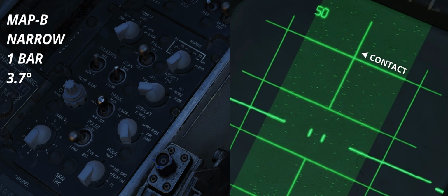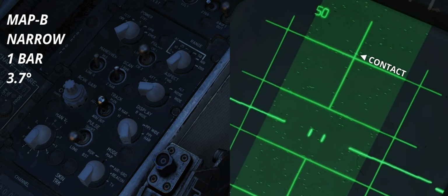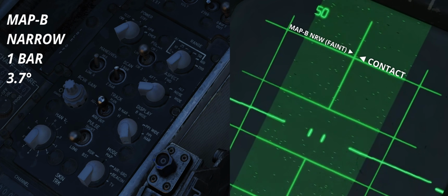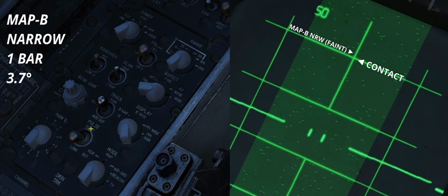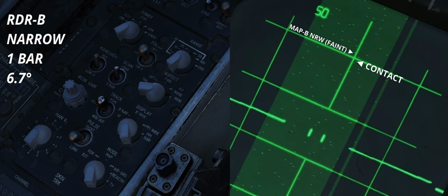Compared to radar systems capable of providing multiple scan bar options, the volume of airspace covered by the APQ-120 is surprisingly tall. Although these options provide great flexibility on paper, in reality, scanning 2 bars can have adverse effects, such as making discerning a contact more difficult.